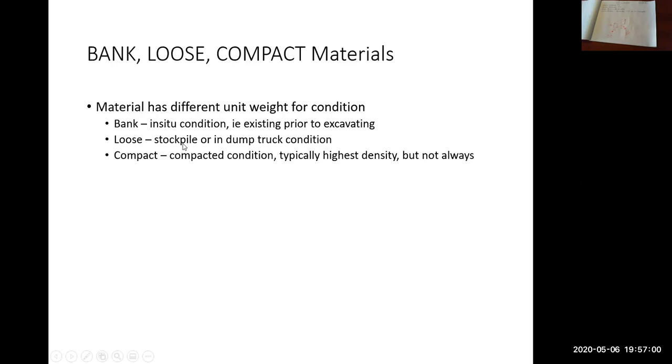Loose is after you've excavated bank. So you have an excavator, you've dug a hole. That material that you dig out, it swells, it gets bigger. The tiny little spaces in between all the particles gets bigger. So maybe you've got a stockpile, maybe you've loaded a dump truck. So it swells. We'll look at that on the next slide.